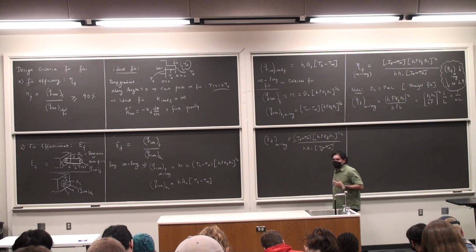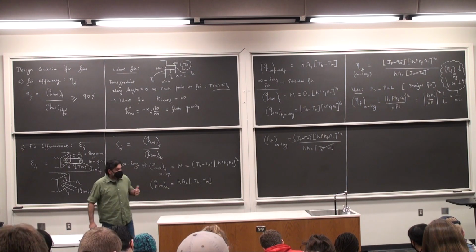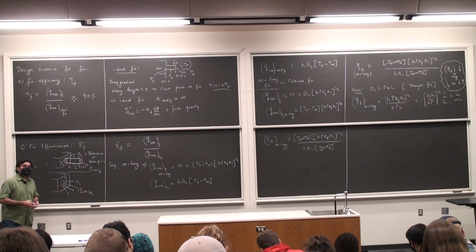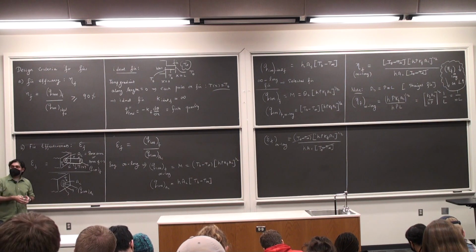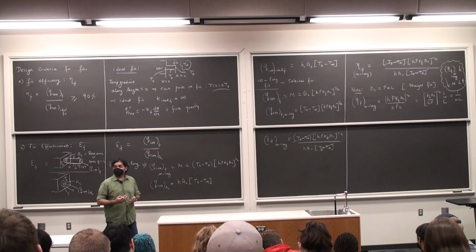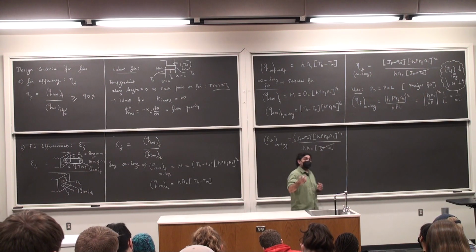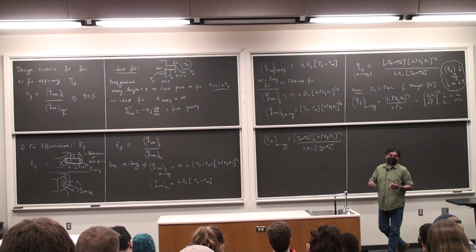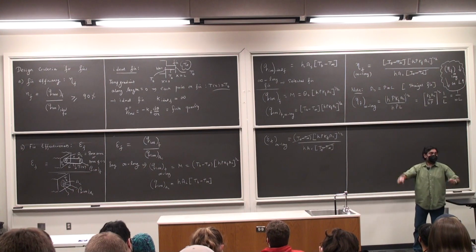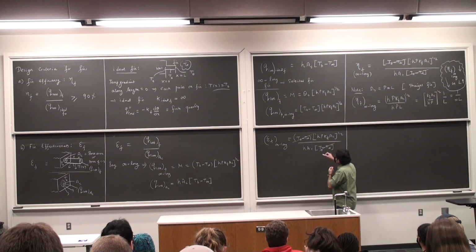And you can do the same thing for an adiabatic fin, which is what you're going to do in your quiz. And I'll write that one down once I'm done with this. You can do this for a situation where the fin is open to ambient convection. You can do this for a fin where the tip temperature is specified. So multiple scenarios. You can do this with the problem we looked at last time as well. You can calculate the effectiveness and see if it is cooling or is it just a waste of our time.